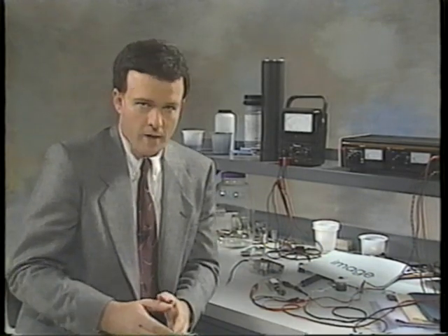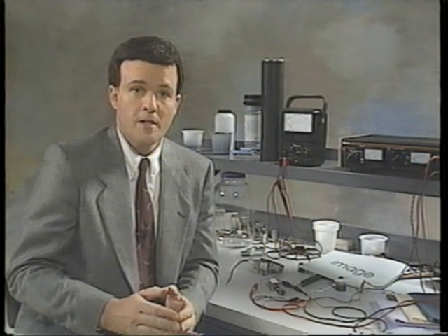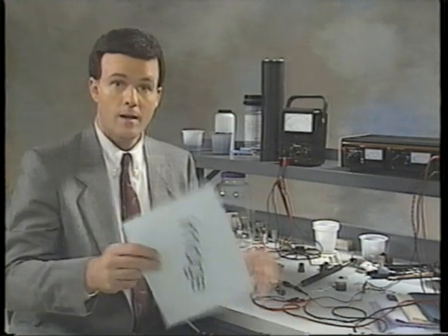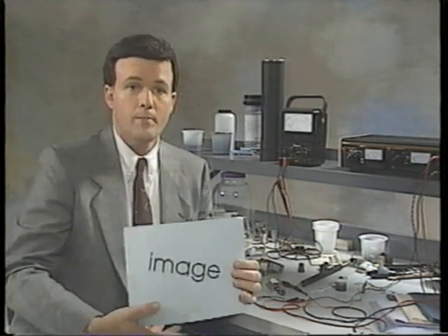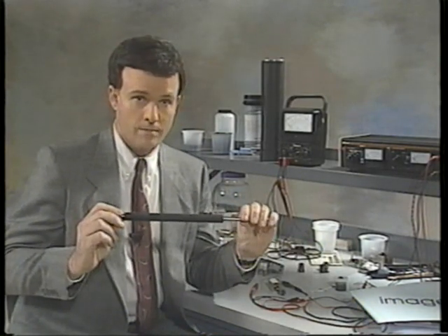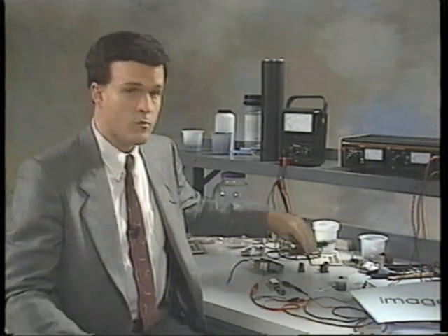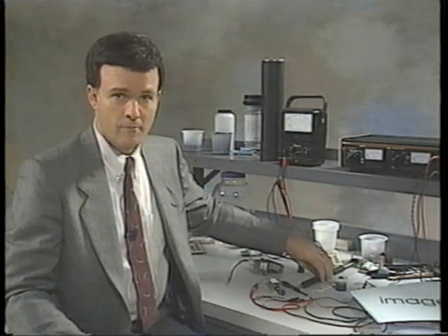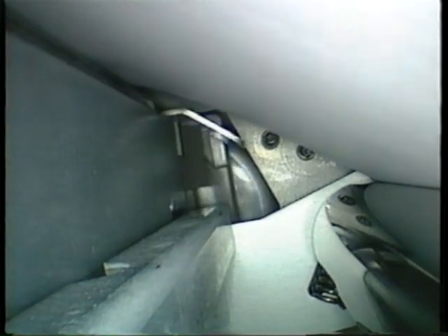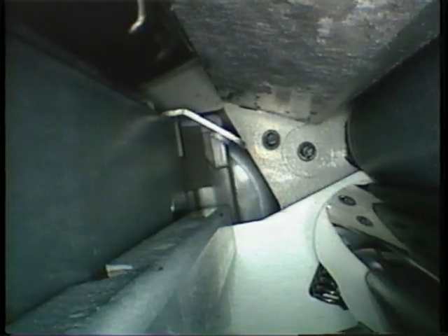Okay, we've covered the basics of transport and separation. The next step is paper registration to prevent skewed images on copies like this. Most copiers use a pair of registration rollers mounted just past the feed rollers. The machine's timing is set so the registration rollers stop just before a sheet of paper hits them, even though the feed rollers are still turning, pushing the sheet forward. This forces the sheet to buckle slightly on contact and align its leading edge with the rollers. The sheet is now square in the paper path, ready to receive an image.